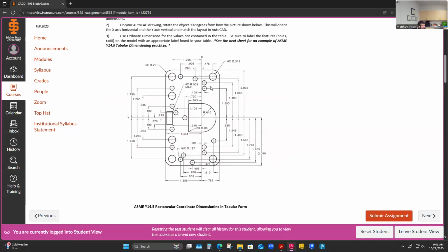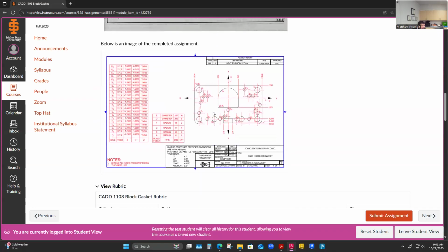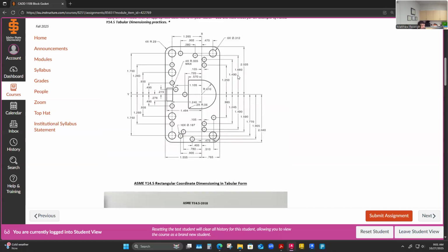And then you'll notice that there are some dimensions we need to carry through. When I look at how I finished mine, there are a few dimensions that I am carrying with arrowless ordinate dimensions. That's the key on this one: we are not using the linear dimension style. I'm going to maintain the accuracy that I was given here. Our dimension style will definitely be 2 decimal places, but it looks like here I'm going to carry mostly 3 decimal places.